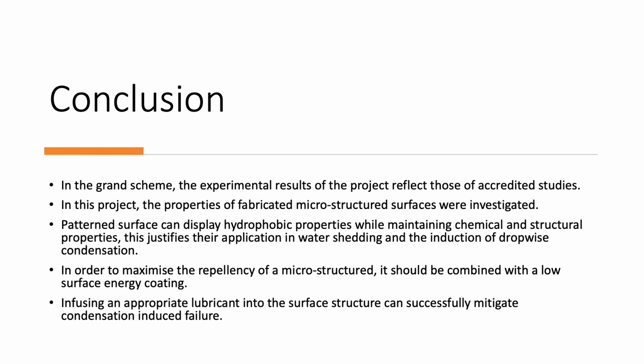When combined with a low-energy coating and an infused lubricant, a microstructured surface can successfully induce dropwise condensation in a robust and efficient manner. Thank you for listening.